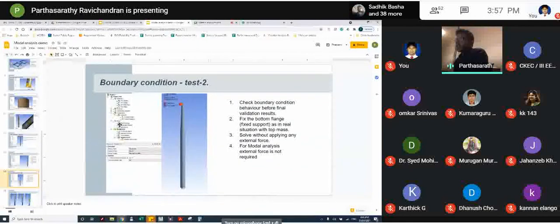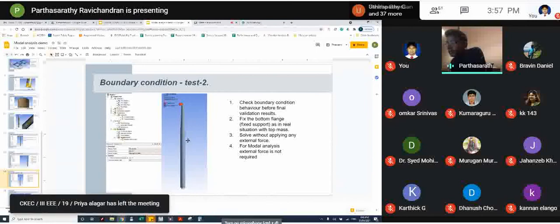So coming back to the demo, in this case we just did this, as I said, by having a point mass at the top. That action is also done in realistic cases. And then we also do another iteration of different materials and check again the frequencies, based on the turbine design.